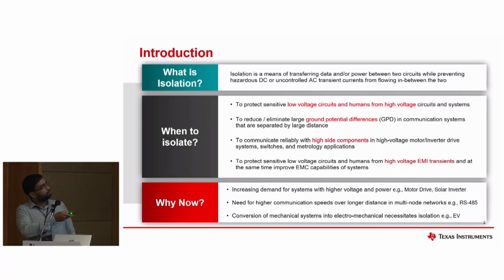The third one here mentions high-side components. Any one of you who has ever used an H-bridge for a motor drive operation knows the high-side switches, the IGBTs sitting on the upper two portions of the H-bridge, need to be isolated from the digital signals that are driving them, because the ground of the digital domain and the high-side domain will be shorted, and the operation will go for a null.